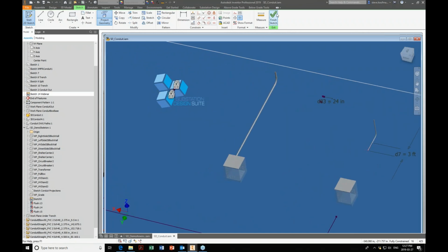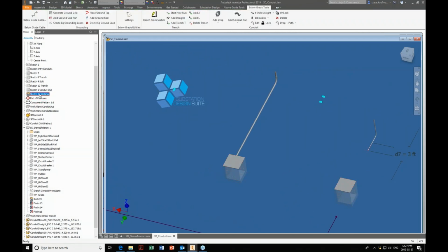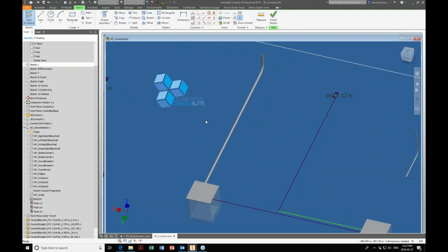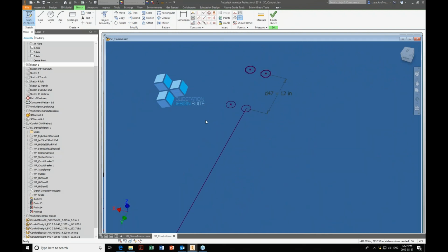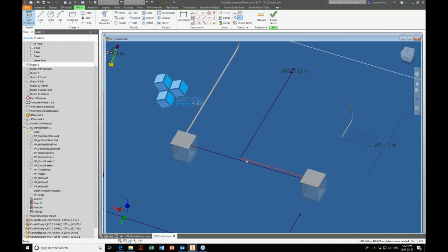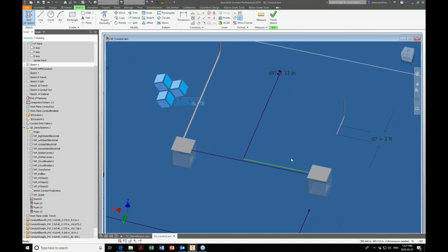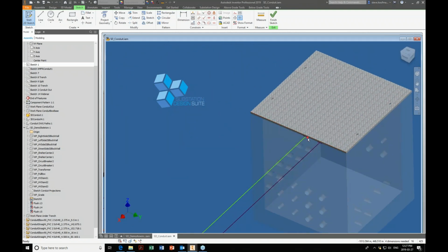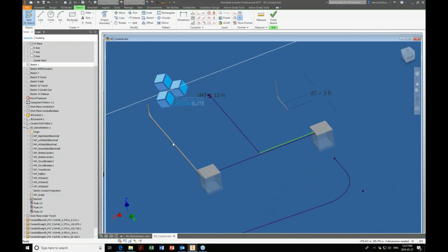So we're going to come out here, finish the sketch, and we're going to look at a finished sketch. Let's turn this visibility off, and let's go back up to sketch 1. This is my primary sketch. And you can see how I have some paths made in here. So that path is just made from the center line. It's just a normal line coming out at a right angle, because we're going to put an elbow in there. The software is going to put the elbow in there, and it's going to come into our projected edge for the pull box. So that's one of our paths.